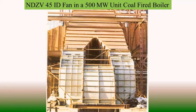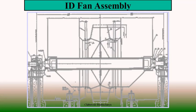So there is a sleeve, so it is a fixed bearing. The bearing towards the motor is a fixed bearing, and as the fan is handling hot gases, there is some expansion. So there is a free end bearing.